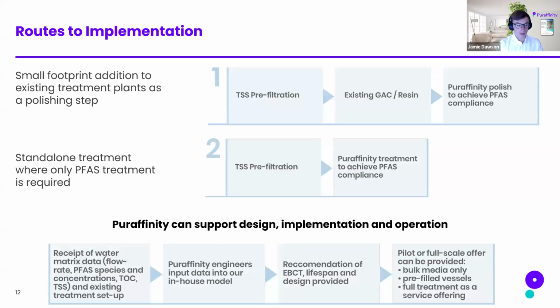To do this, we require some basic data: flow rate, PFAS species and concentrations, TOC, TSS, and any information on existing treatment. And we can pass it on to our engineers who put that through our in-house model.